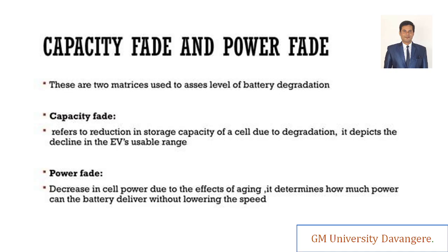So that is the reason there is a decrease in the cell power. There is a decrease in the maximum power. The actual maximum power would have some rating, right? So that we cannot expect in the batteries, due to the aging factors, right? So we have to see the aging factors due to the various reasons. It will also impact your EVs, such as poor acceleration of the vehicles, all right? And also while climbing, the vehicle cannot deliver the high current because of the voltage sag.